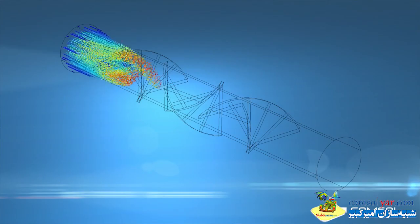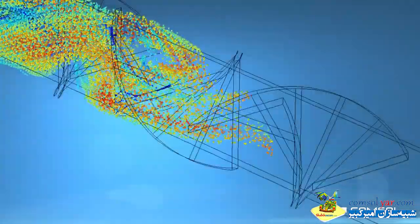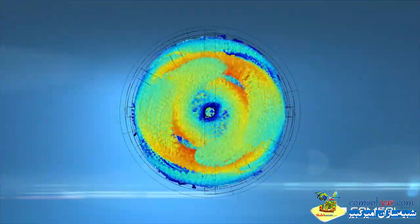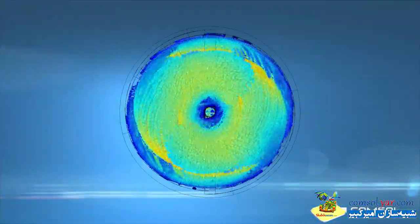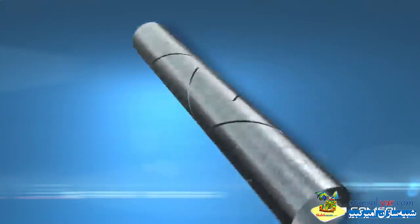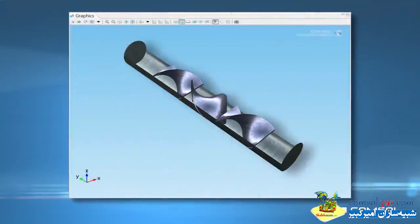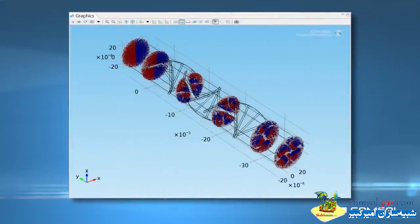The static mixer is comprised of a small cylindrical flow channel with stationary cross-sectional blades. When a fluid is pumped through the pipe, the mixing blades cut up the flow field, causing the particles traveling through the mixer to displace relative to each other, creating a mixing effect. This model studies the flow in a twisted blade static mixer and helps analyze the mixing performance using Poincaré maps.